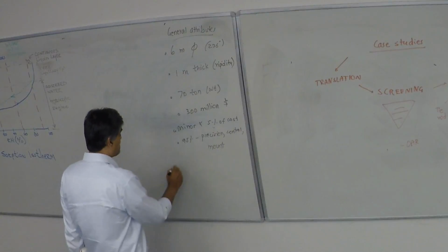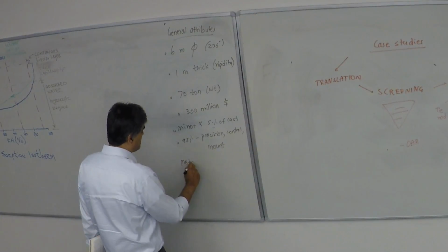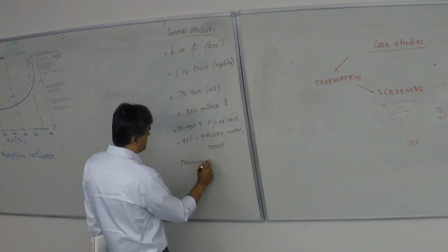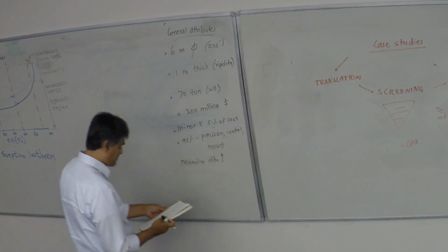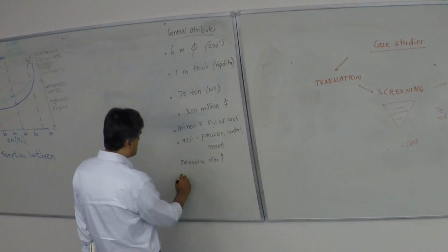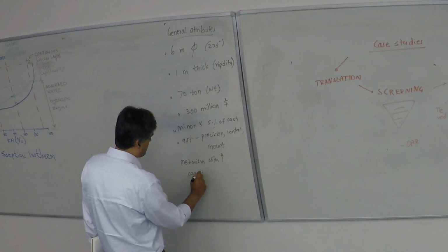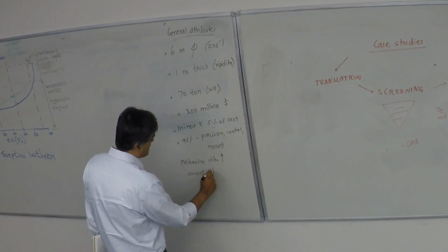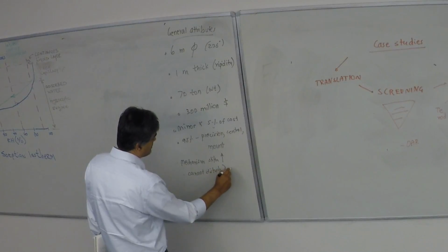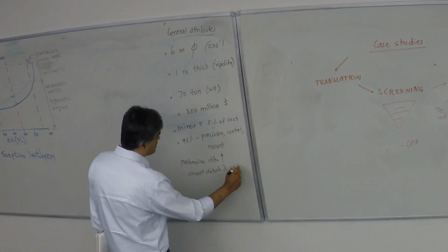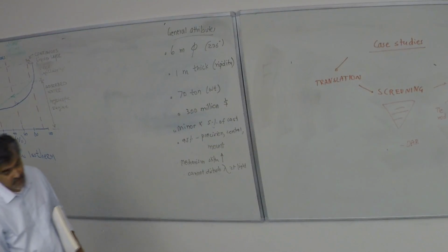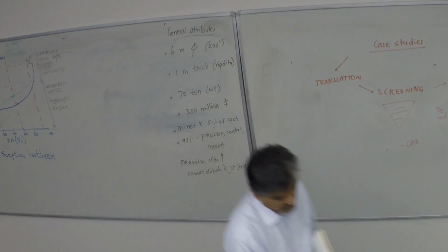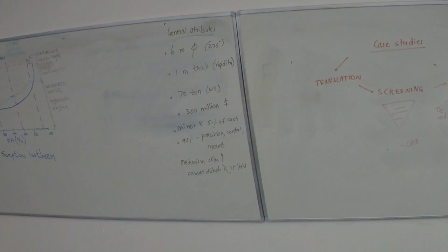So the key thing is the mechanism has to be very stiff here, very high stiffness, because of the precision, and you cannot disturb the wavelength of the light, because all that results in erroneous reading. So there are a lot of strict requirements for something like this.